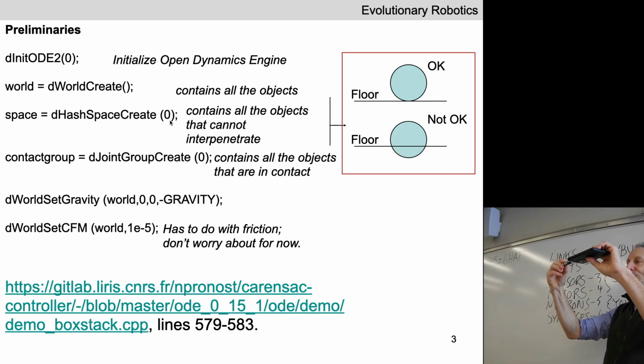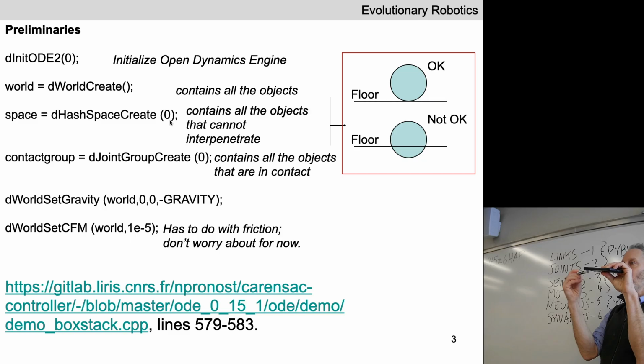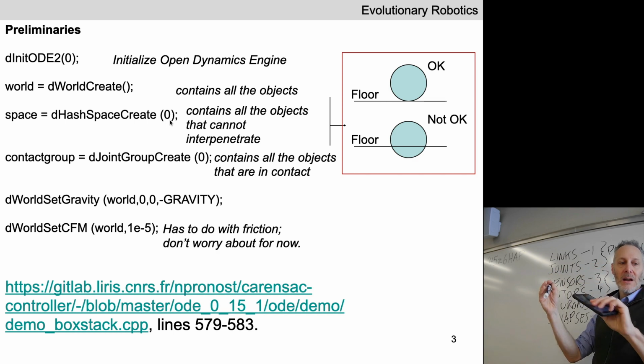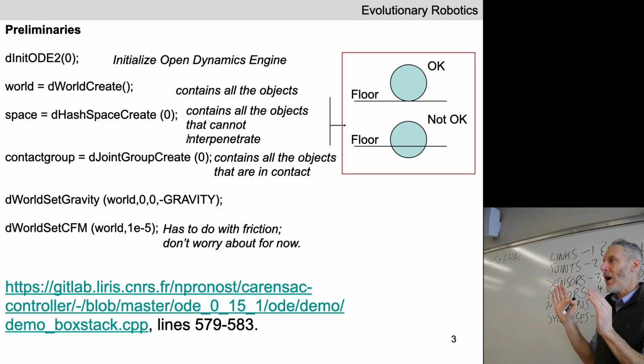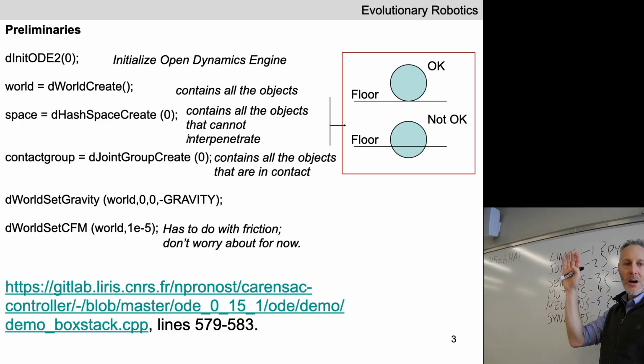In PyBullet, you might place the upper and lower arm touching one another or even maybe overlapping a little bit, which means by definition they're already interpenetrating. And PyBullet, like the ball in the floor, might try and push these objects apart. So you need to tell the physics engine, do allow these objects to interpenetrate. They're supposed to be touching one another, and they're allowed to also push within one another to a small amount. Don't try and pull them apart. Yeah. So there is a subset of objects in your simulation that should not interpenetrate, and some that should.